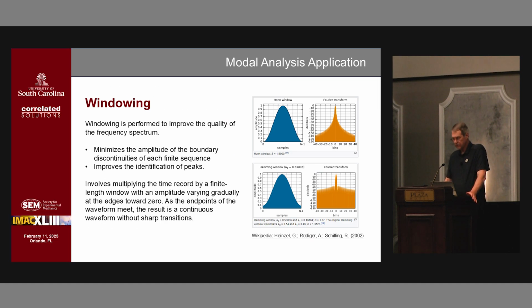As far as the windowing is concerned, you know the windowing function has its own issues. You have to be sure you have enough understanding of what frequencies you're looking for, so that you don't dampen out something you're actually seriously trying to locate. In our case, it's very important because we're measuring displacements, not accelerations.